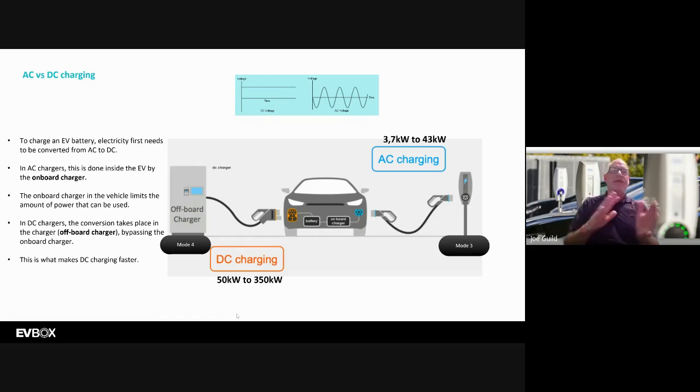So in this case too, if we talk about sectors, what are we talking about? When you buy an electric car, you have a charger at home, and if your charger can charge your car within 8 hours, which is about the maximum that you want, because that's about how much you sleep, so when you wake up in the morning you have a fully charged car, you don't need DC charging for that. Remember, DC charging is much more expensive. Those big stations are very, very expensive compared to an AC.